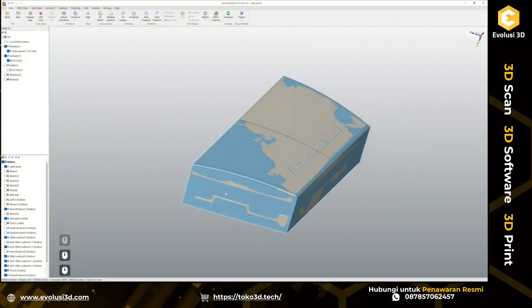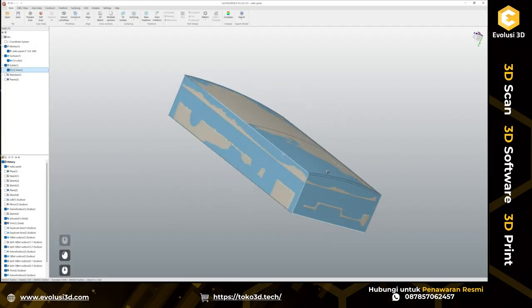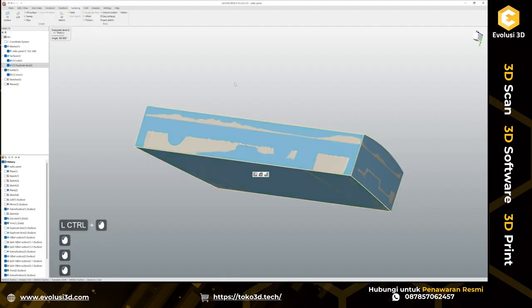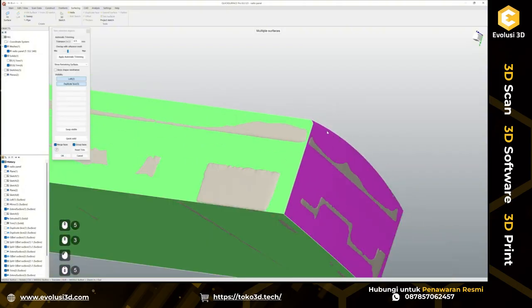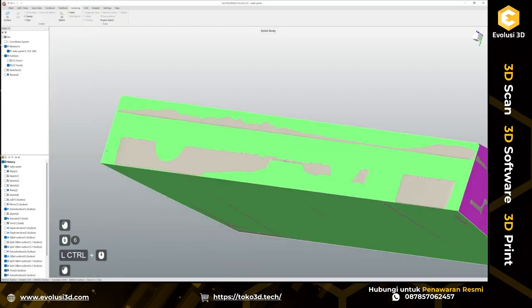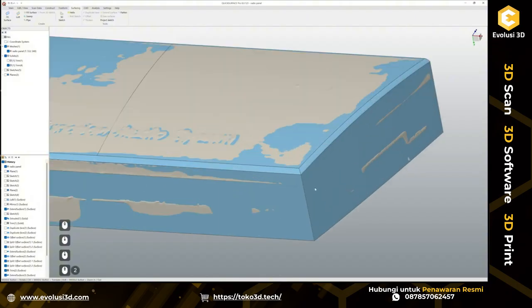Okay, so once I have completed this, where is my solid? Actually, from here I'm going to probably simply duplicate those two faces and trim all this into one single solid. Okay, looks good.